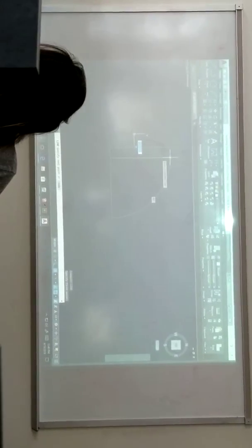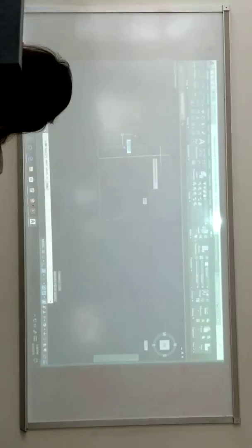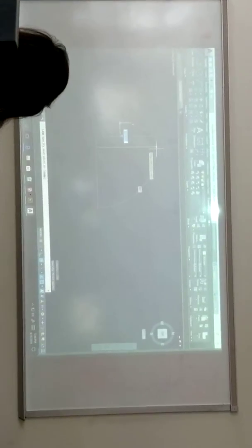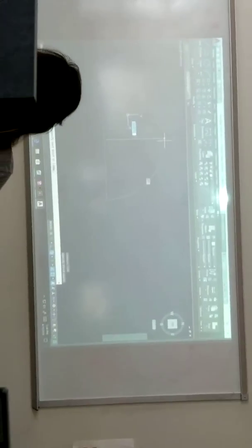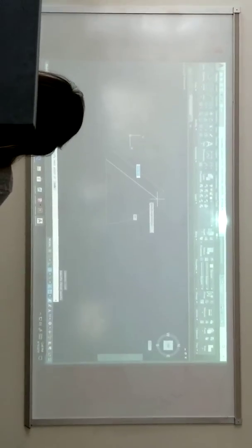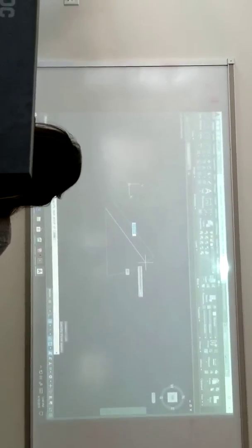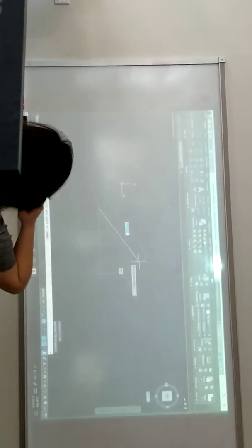You see this little thing, polar, right here that says polar 90 degrees? It lets me know that not only am I at 90 degrees, but I'm at this length. This is my polar tracking. Now I'm at 52 degrees. Now I'm at 35 degrees. I am able to track my movements. Illustrator does not allow you to do that. The other thing is, because I can track my movements, I can say, okay, give me 5,000.